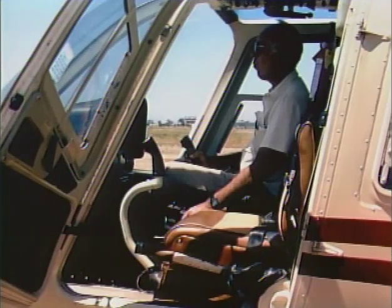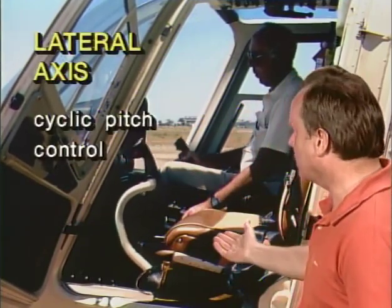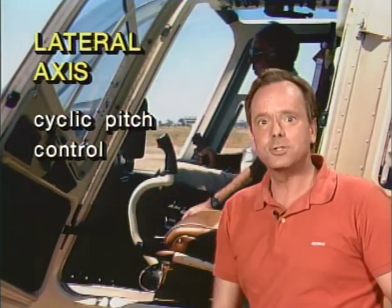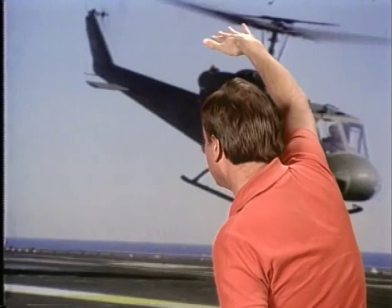Now, they also ask you, how do you control movement about the lateral axis? Well, that is pitch, and that also is controlled with the cyclic pitch control. So you do that by moving the cyclic fore and aft, and that changes the pitch of the helicopter. Now, they say, let's assume that you're in forward flight, cruise configuration. How do you change direction of this helicopter? Well, the way you do that is by tilting the main rotor disc in the desired direction. The cyclic control really does it, but it tilts the main rotor disc in the desired direction.